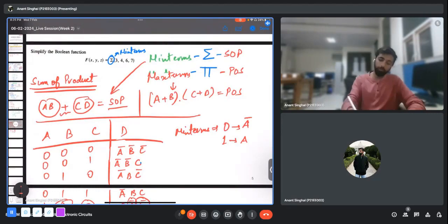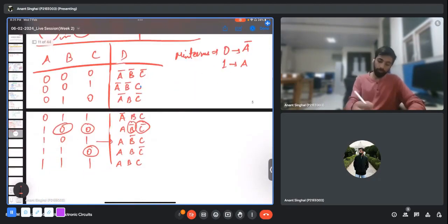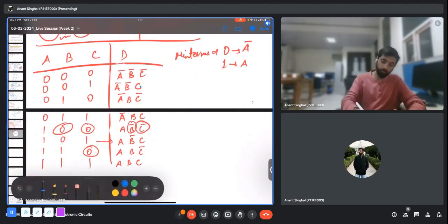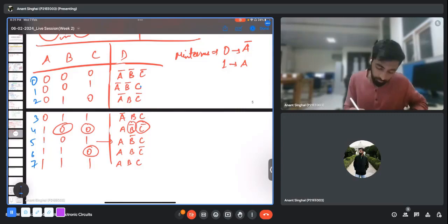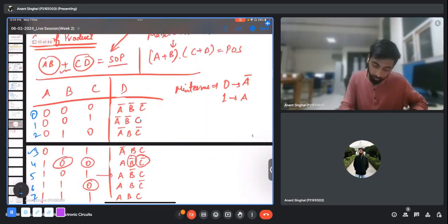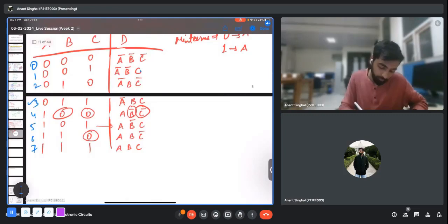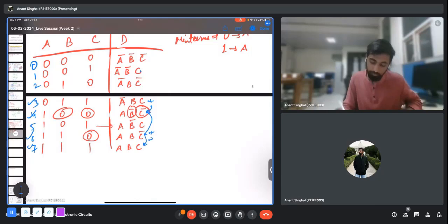So here min terms, if I write in the decimal value, are basically 0, 1, 2, 3, 4, 5, 6, 7. Now the given question has min terms 3, 4, 6, 7 basically. So first of all, we can easily write the min terms as the addition of these four terms, that is this plus this, then I have the sixth, plus this, and then this.